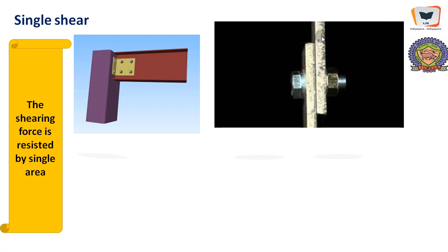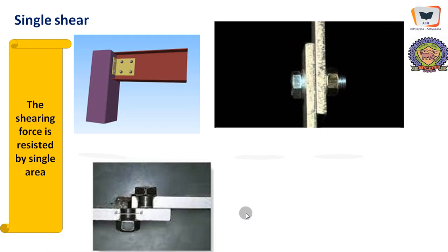If we have applied force F over here and F over here, the shear generated in the area of cross section of the stud will be equal to F by A. And this is the typical scenario of the failure. This particular portion of the nut has come this way, and this has given this way. There is a hole that is being created.